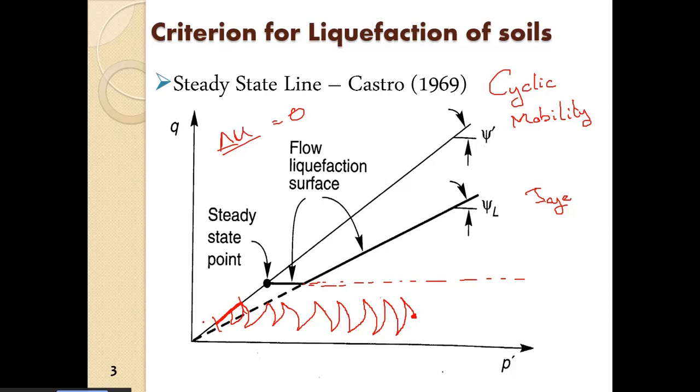All right, and of course at that point, if we apply monotonic load, the shearing of the particle will take place in this direction. All right, it will go up. So definitely that means there is dilation in the sample. If there is dilation in the sample, that means the pore pressure developed will be negative during the monotonic loading.